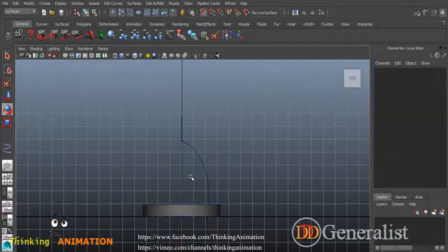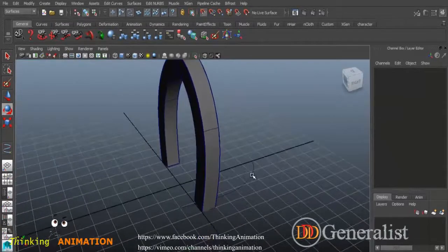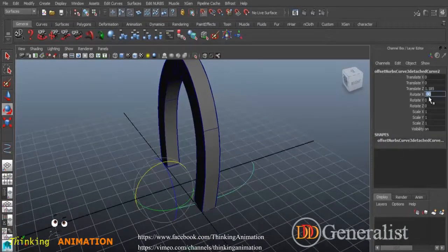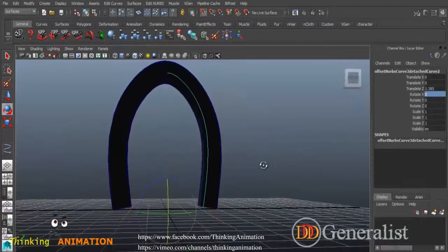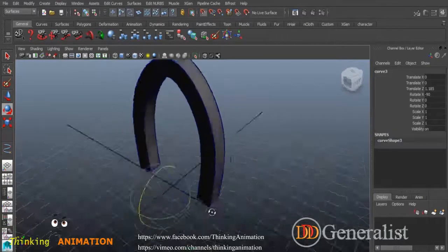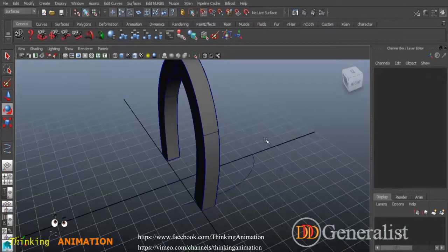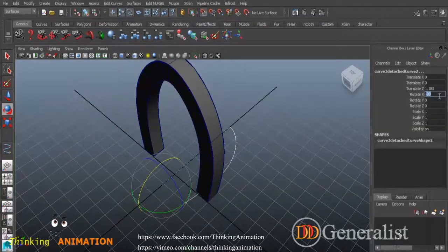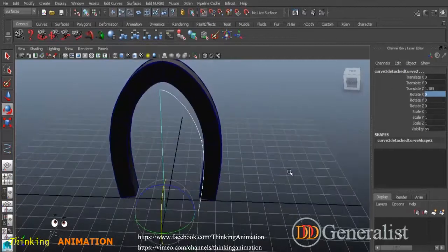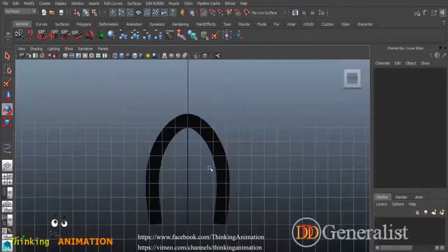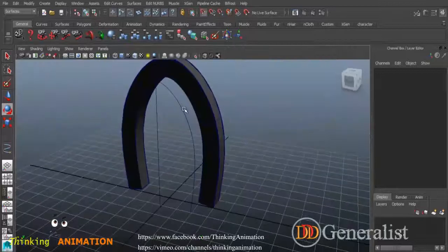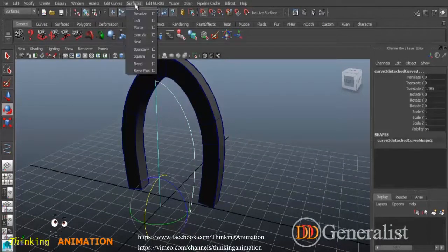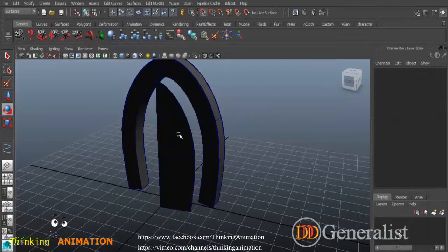Because in the front view they were not intersecting actually, so I went to the top view and I got the shape back. So what I'm going to do is place the 0 right here and you get the shape back here. Okay, I'm going to undo this because I don't want to delete this portion of the line right here. Select both lines, press 0, and you get them right here. So when I get them here, I select them both and click Loft. And this way you get a door here.